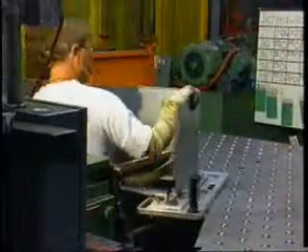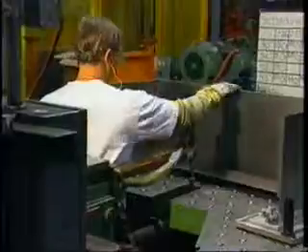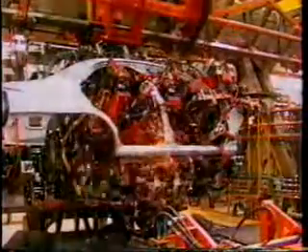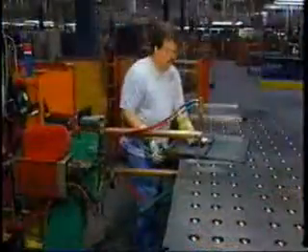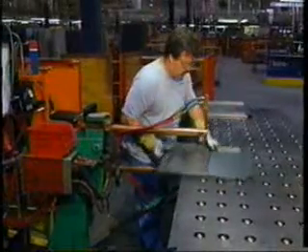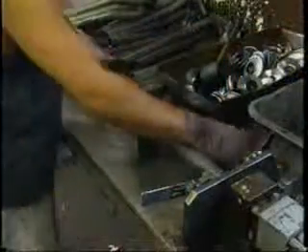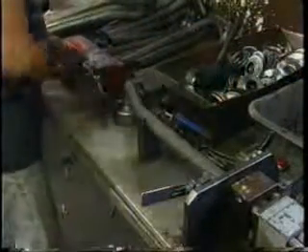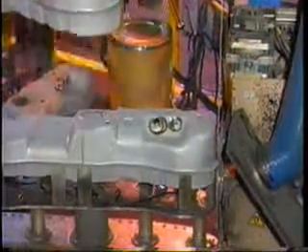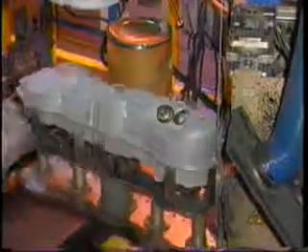All resistance welding methods use either semi-automatic or automatic systems. With semi-automatic machines, the operator either positions the workpieces between the electrodes or positions a portable welding gun around them and pushes a switch to initiate the weld. Welding then proceeds according to a pre-programmed sequence. Automatic machines feed workpieces into the machine, where they are welded and then ejected without operator assistance.